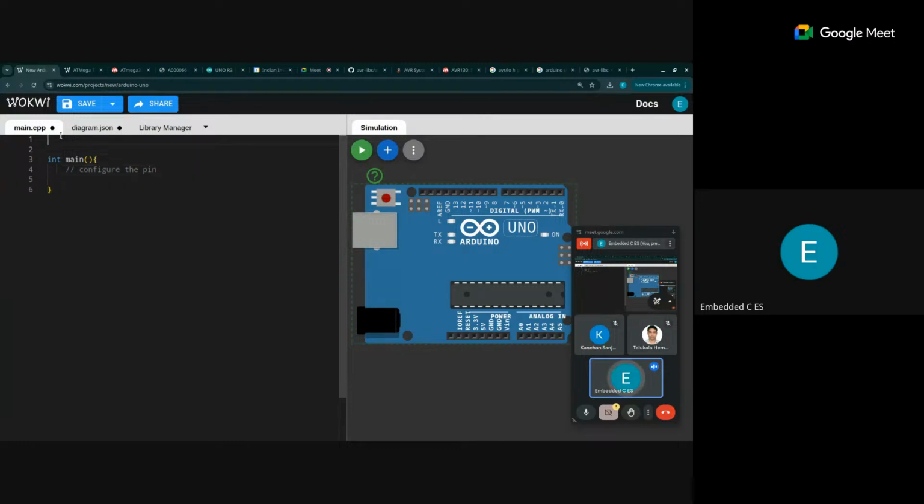Now we can also set it like this in the LED pin. So what is our LED pin? It is PB5, but we don't know what to do, right? We set it using the DDR register, the DDRB register for the B port. DDR sets the direction, so we have to set it to output.